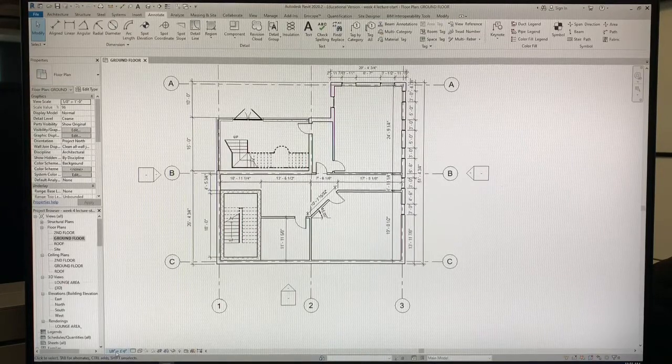Put it on a printable sheet, right? We should put this drawing on a printable sheet first so that we can determine what our viewport scale is. Remember, in Revit, our annotation scale is our viewport scale. So prior to doing any dimensioning or adding text of any sort, we should put this drawing on a page so we know what our annotation scale is. Therefore, we will know what the result of our scale would be based on our text. So here's what I want you to do. Let's start a sheet first.